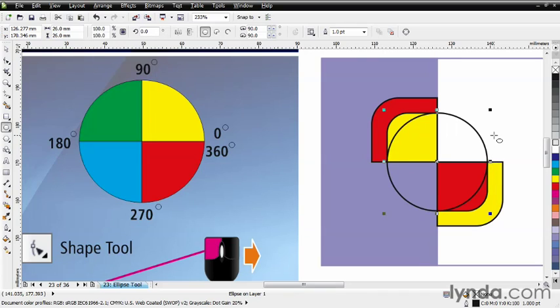Release my mouse, then my keyboard shortcuts. As you can see, the ellipse is selected. To deselect, just click once on the page. Now we're going to do it again. Click in the middle and then Control and Shift. Now as I move along, you'll see there are two midpoints. There's a midpoint right there and it snaps to it, and then there's one more right there it snaps to. For convenience, just go all the way out to the other one and then come back. The first midpoint you come to on the way back, that's the one. Release, click and deselect, again, click, Control, and then snap to that first midpoint there.